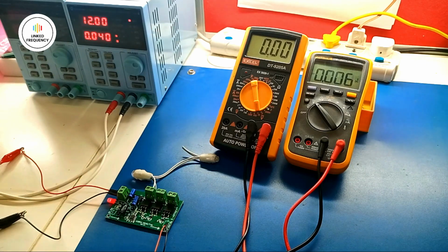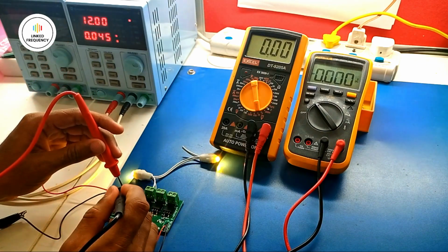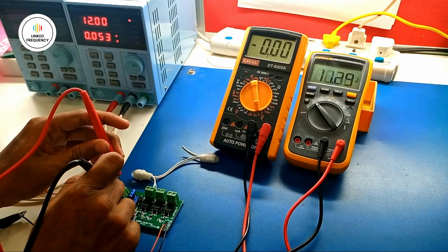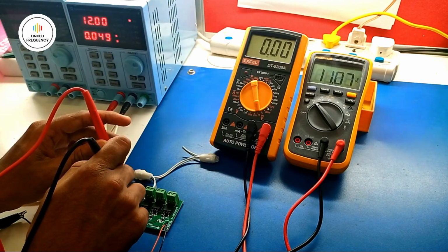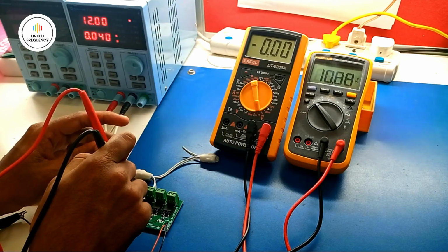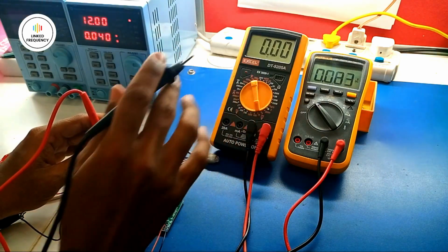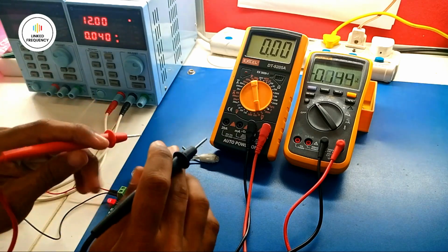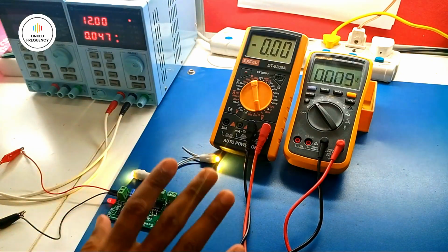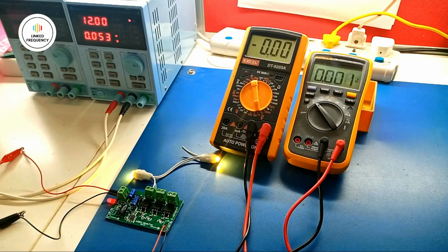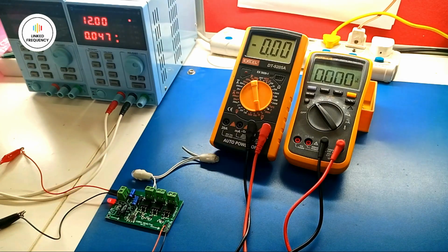So VDC is selected over there, and I'm going to connect the positive pin here and the negative pin here. It is showing pretty much the same voltage, 11.27 volts and 10.97 volts. It is varying in the same range as this particular multimeter showed. At such a high voltage level, it doesn't show any difference. If you are measuring very low current or low voltage, then the difference between these two will be visible to you. Now let's start with how to measure the current, or DC current, in these two multimeters.